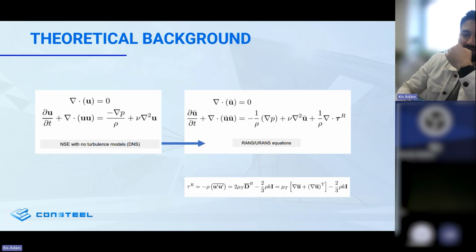For instance, this Reynolds tensor, which models viscosity and requires an initial estimation or boundary condition at the inlet side of our simulation domain. Another simplification is that we seek a steady solution. So instead of unsteady Reynolds averaged Navier-Stokes equations, we neglect these time-dependent terms. So this will result in quasi-static structural loads.